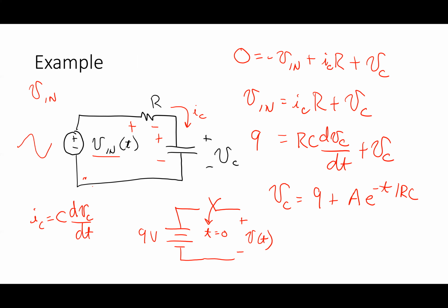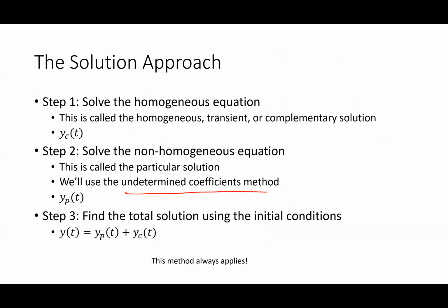That's actually what makes the complex number thing really work out well for us. Because if I have a sine wave going in, the only thing that's going to change about that sine wave is its magnitude and its angle. So the only thing that's going to change is its phasor. That static phasor is the only thing that changes. And that's what makes this useful to us. So essentially, we always guess that our output is going to look like our input.